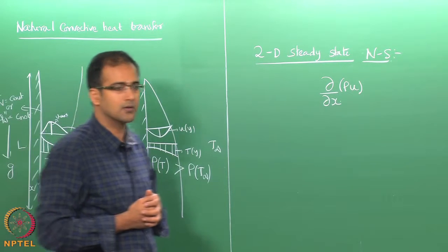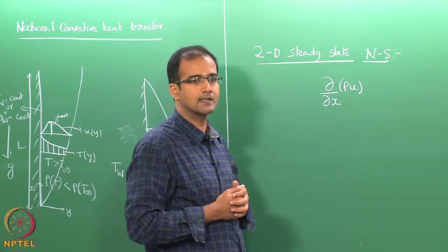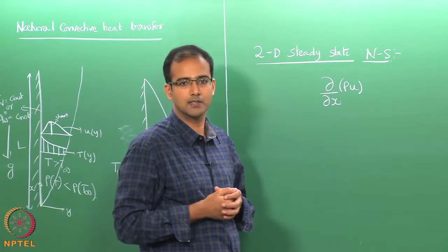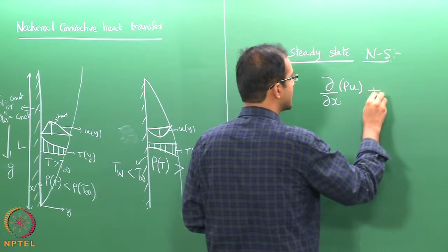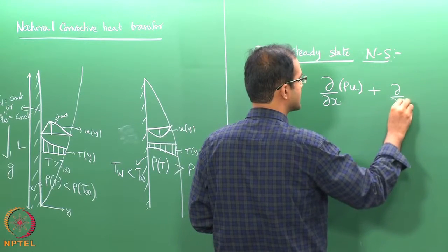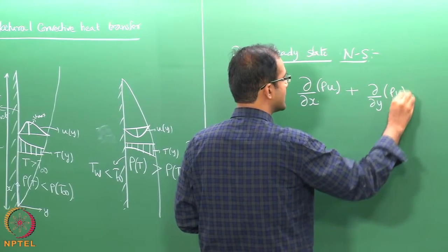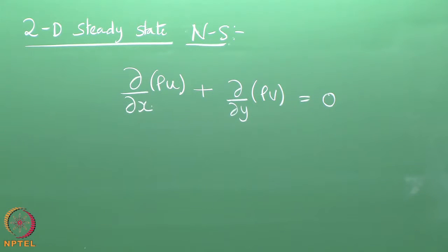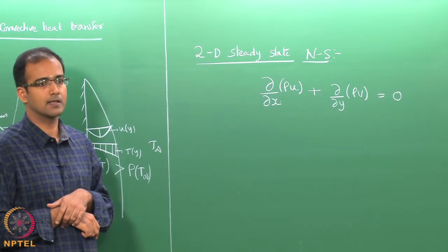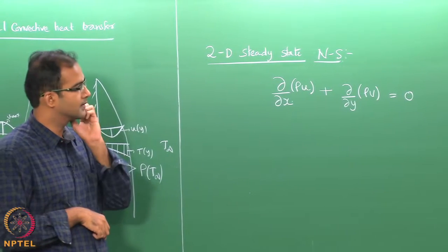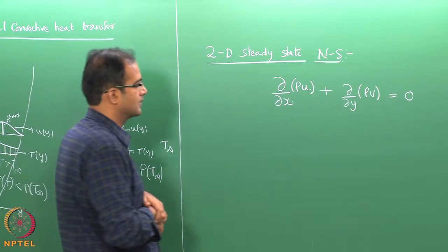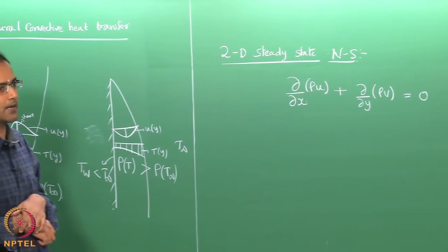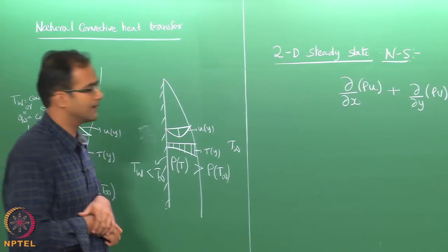Okay. So, locally it will look like it is a compressible fluid, because the density keeps varying with position. So, you cannot directly, at a first cut, say that this is an incompressible approximation straight away. We cannot directly pull density outside the derivative and say it is a constant, right. However, it was shown later by Boussinesq.